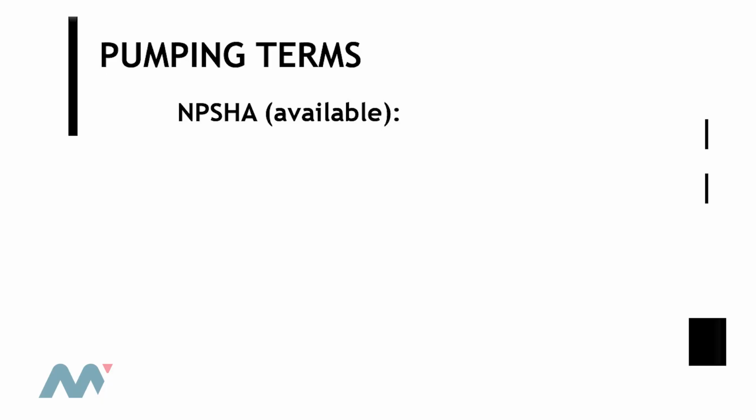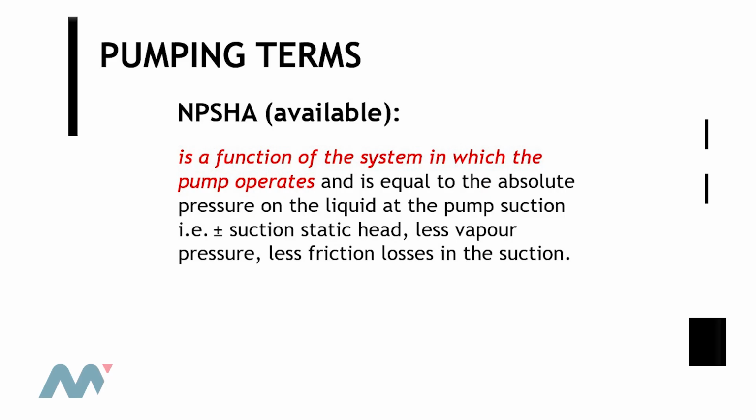There is NPSH available, which is the pressure that belongs to the system, in other words, the suction system that feeds the pump with fluid. It's a function of the system design, and it includes losses in friction and so on, and a static component.